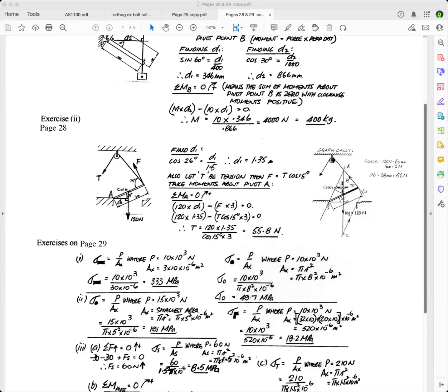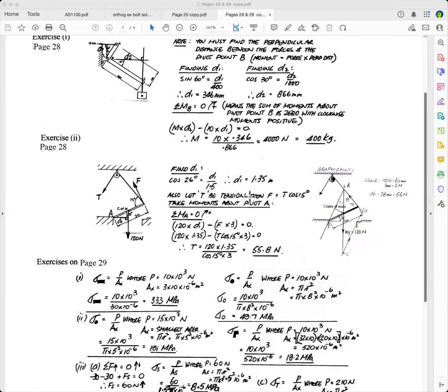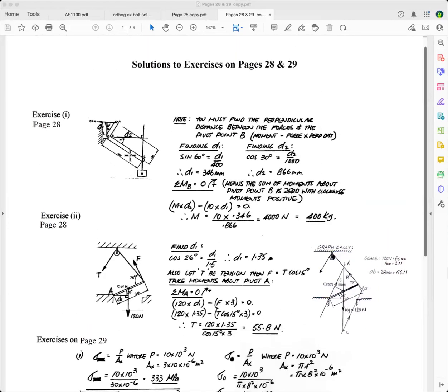And then the last force that you come to is AB. And it's got to go through B there. And so it's that cable there. And so you can work out, you just measure that distance there using that scale, and you can get pretty accurate. Look at that, 56 and 55.8 there. So that's the 3 force rule.